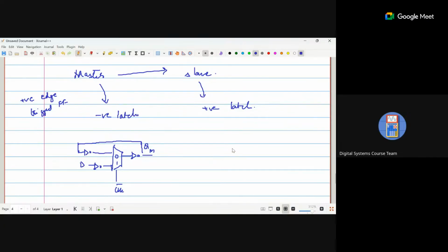Okay. And then we have another positive latch here. So this will be 0, 1, and you will have clock as usual. And again, there is an input. Here again, there is another Q which goes all the way to here. This will be the final Q. Okay. And this D, you will get it from this master. This is what will drive your slave.